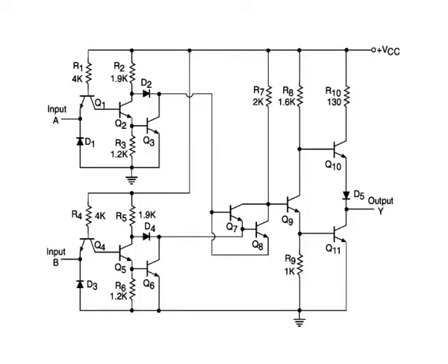Exclusive OR gate. Figure shows the internal schematic of an XOR gate in the standard TTL family. The schematic shown is that of one of the 4 XOR gates in the quad 2 input XOR gate. We will note the similarities between the circuit and that of an OR gate. The only new element is the interconnected pair of transistors Q7 and Q8.